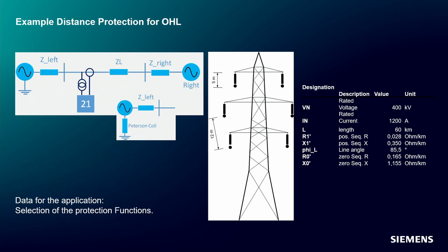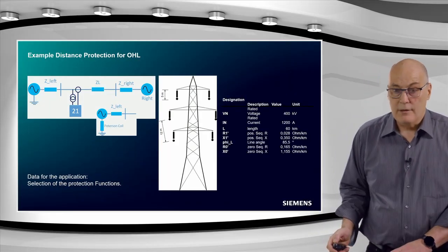For the Peterson or resonant coil grounded systems, obviously one needs to consider differently, because ground or single phase faults are not real short circuits, and are treated differently in those cases. But that is a different subject. Today we are looking at effectively grounded systems.